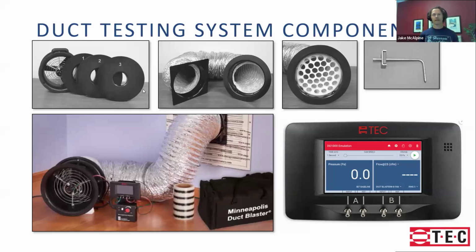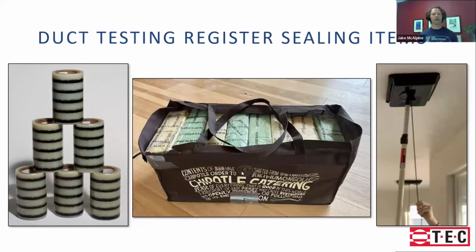We've got some flex duct that helps connect to the system. There's a flow conditioner when you're doing the depressurization test to help make sure we maintain accuracy while we're testing. And then you'll need a static pressure probe and a gauge. So those are your system components that you'll need to do the duct leakage test. Okay, and now all that comes like in a Duct Blaster kit. Yep. That all comes standard.